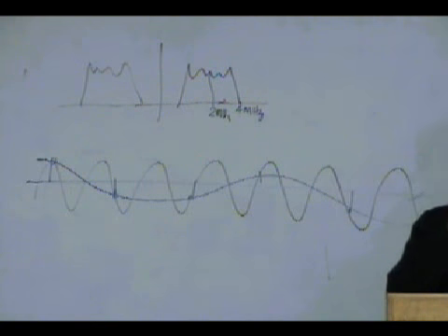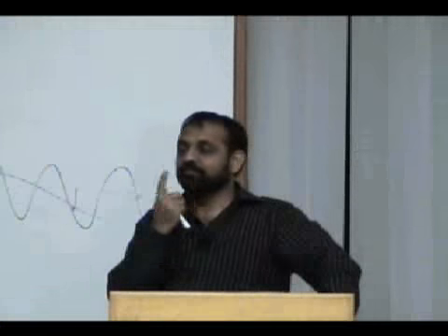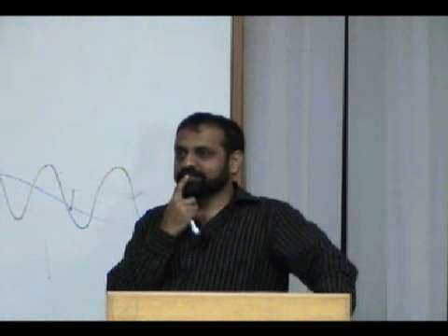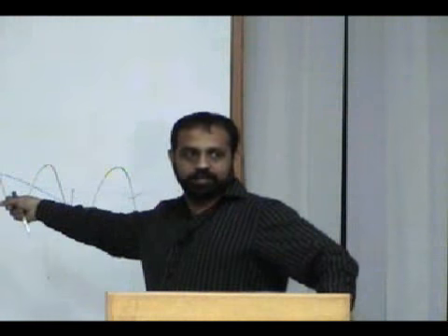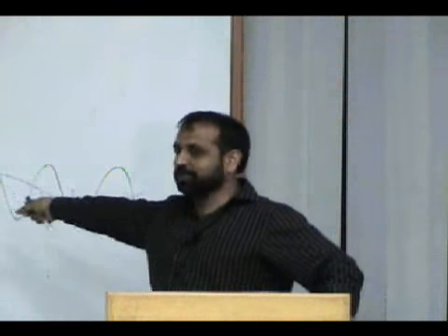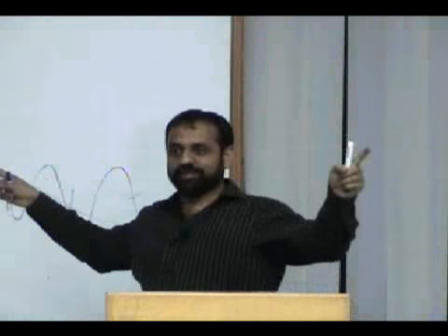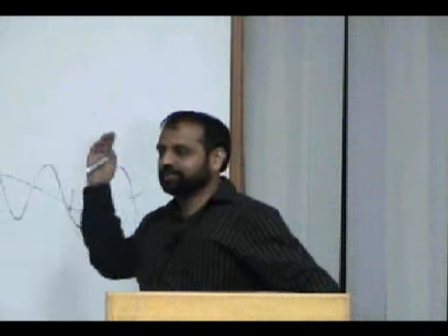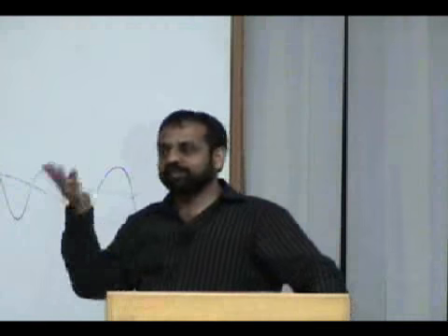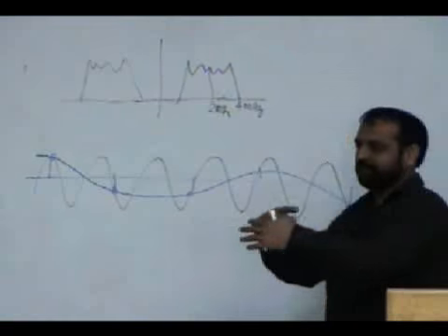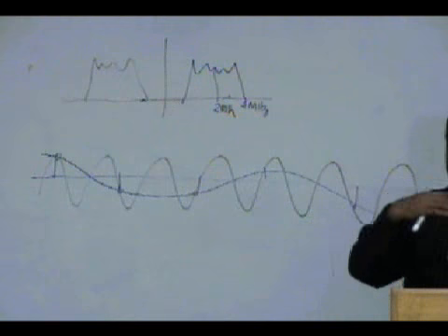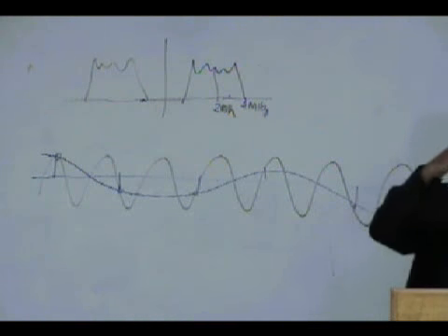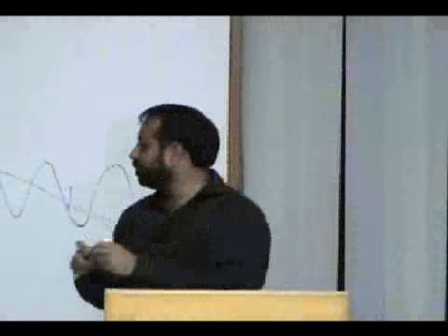Aliasing. What does aliasing do? Which 2 frequencies? You see, this frequency may already be there in the signal. Okay? This frequency, what you have generated, is not the true content of your signal. This is because you could not sample fast enough. It has generated another frequency, which may already be there in your signal. It will go and corrupt that. The effect will be as if this particular frequency is being added into the original frequency, because we saw a spectrum.